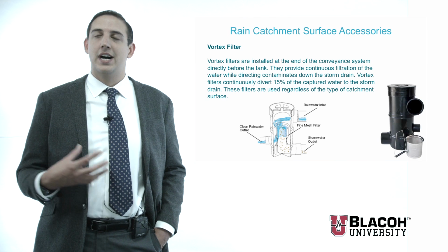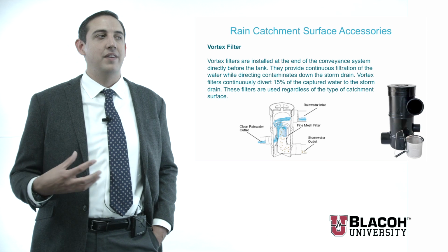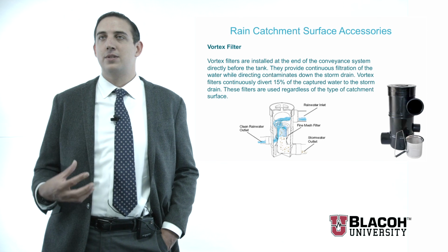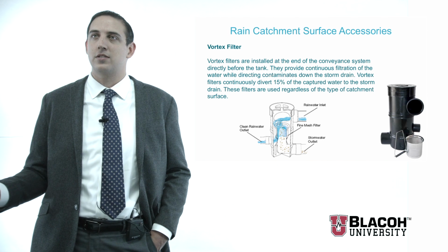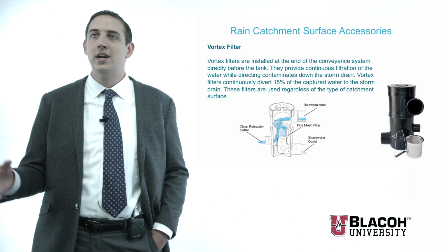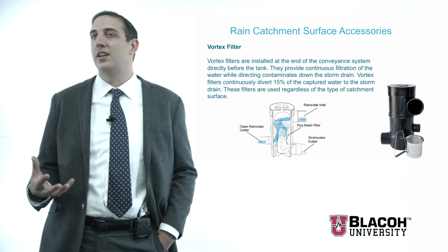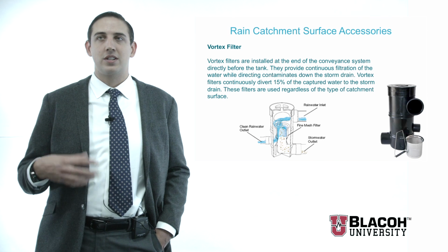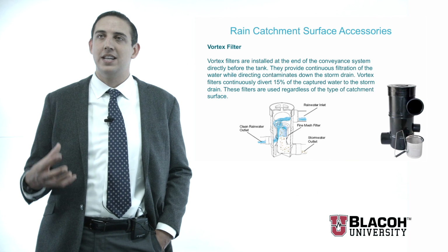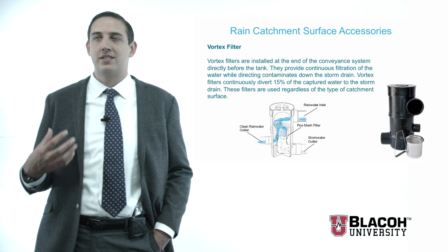So good concepts that are still being developed into adequate technology, but really the point of any kind of treatment at your catchment surface is to, one, either avoid transferring water to your system during that initial surge of rain, and to remove any very large contamination. In this case, I'm talking about particulate matter, turbidity. You're not going to be able to remove bacteria or discoloration or any of those types of contaminants at the roof surface. You have to do that in your actual treatment system.